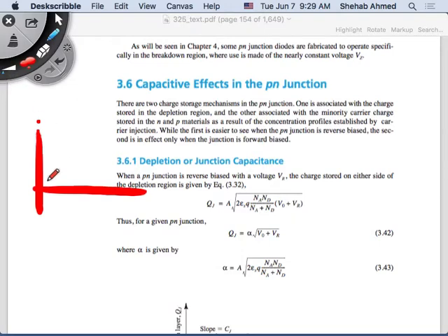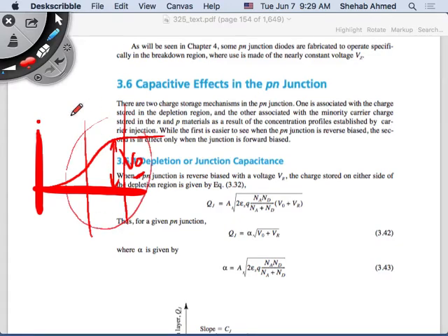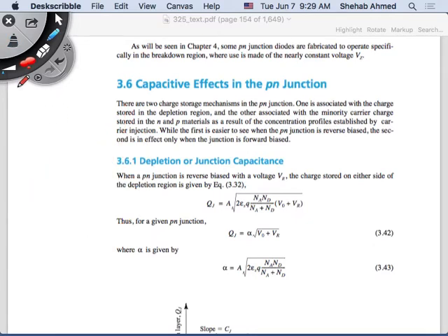building up? We saw a plot where it was building up across the depletion layer, right? The voltage, this was V barrier, or V0, right? So this voltage was building up. So this junction or depletion layer is like a capacitance, we said. And this is proof that the voltage cannot change instantaneously across a capacitor. And the same thing here, voltage will not change instantaneously across a junction. It will take time. So it's like a capacitor. So capacitors have time-dependent changes of voltage and current across them.